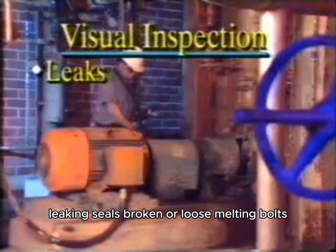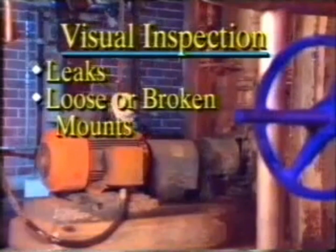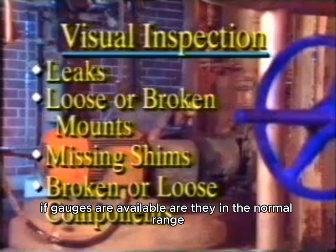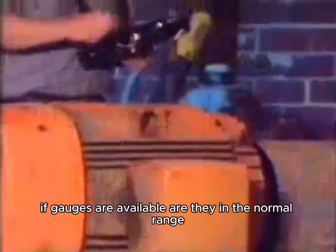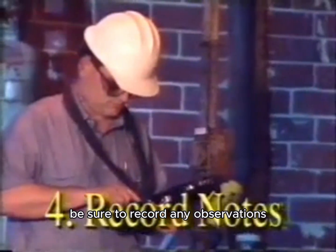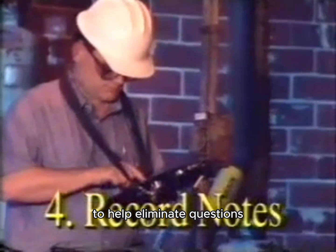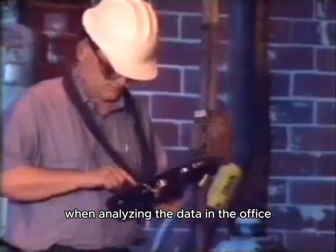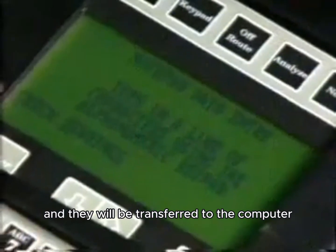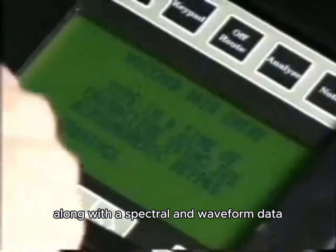The third step is to visually inspect the machine, checking for obvious problems such as leaking lubricants, leaking seals, broken or loose mounting bolts, shims slipped out from the feet, and broken or loose components. If gauges are available, are they in the normal range? Be sure to record any observations to help eliminate questions when analyzing the data in the office. Some analyzers have the ability to store notes, and they will be transferred to the computer along with the spectral and waveform data.